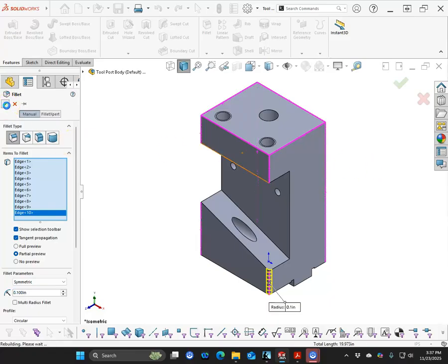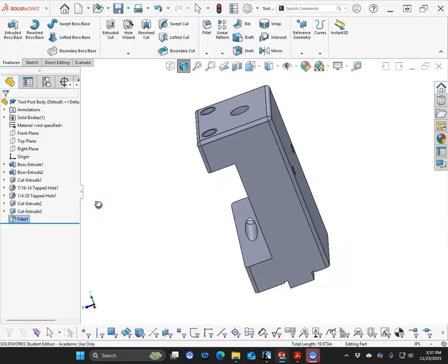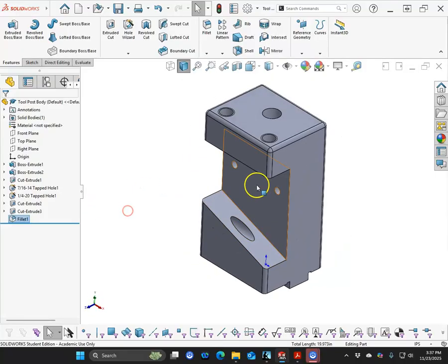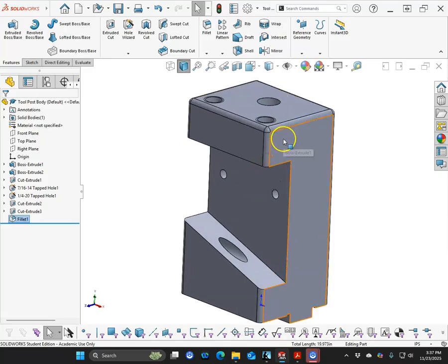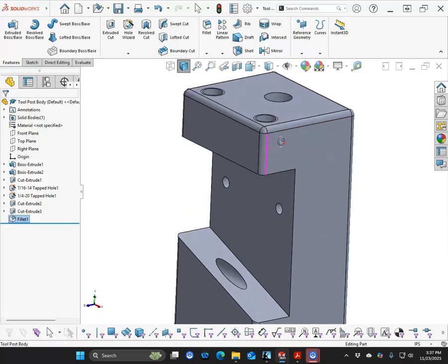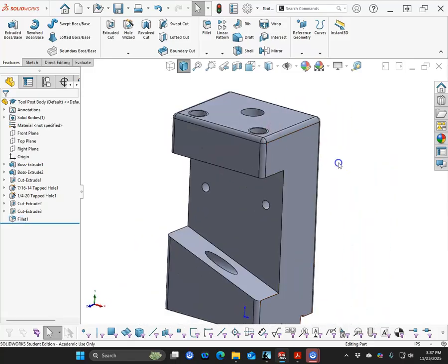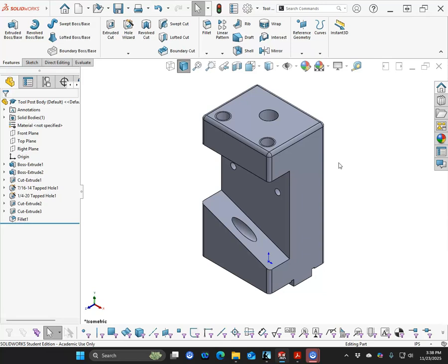So from a casting, the fillet's going to be fine. From a machining standpoint, if I was making one of these out of aluminum or a block of steel, I would really want to consider the horizontal fillets because they take more to set up. The roundover tools, I might consider just putting a heavy edge break as a chamfer or something else on those to make them work.